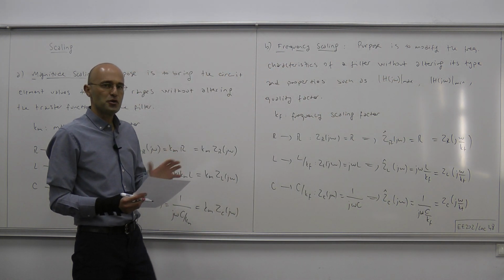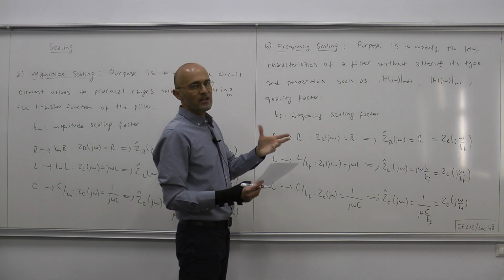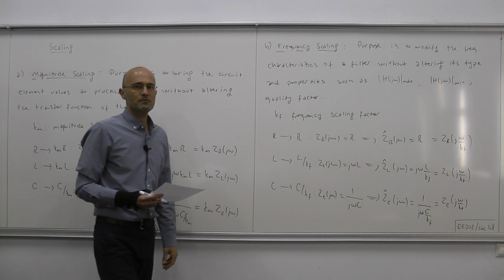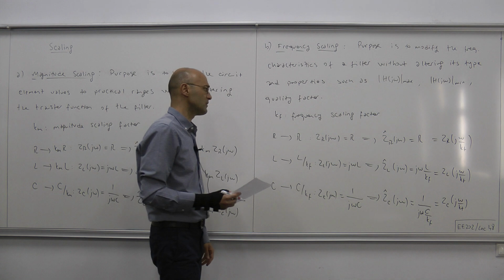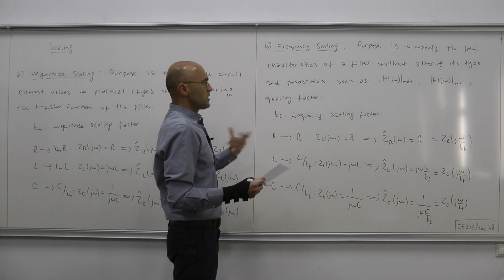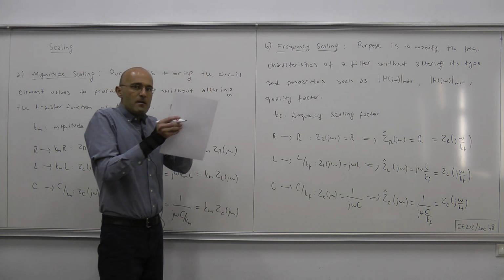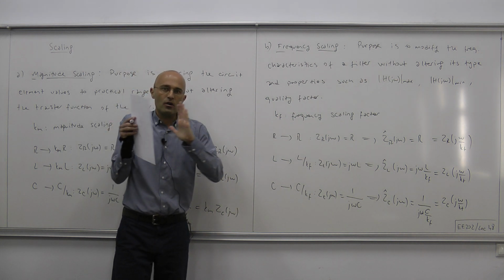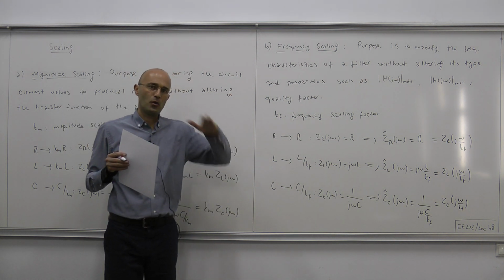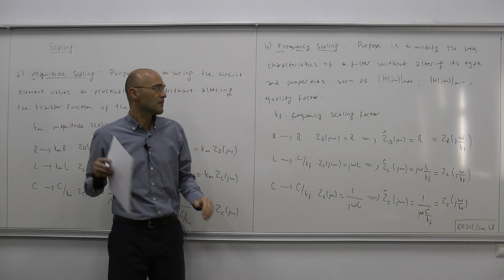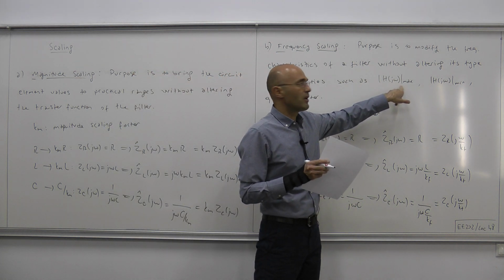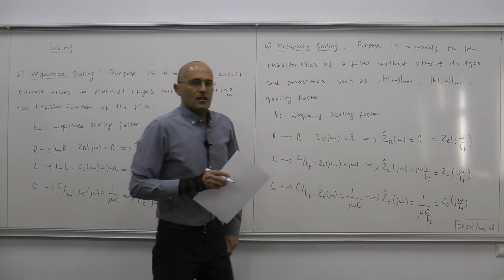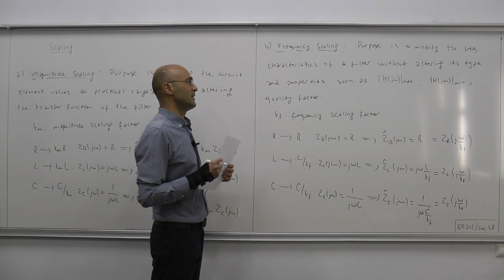And that produces the effect on the transfer function of the filter, such as squeezing the shape of the gain characteristics, or stretching the gain characteristics. Note that while squeezing or stretching, things like the maximum value or the minimum value don't change.